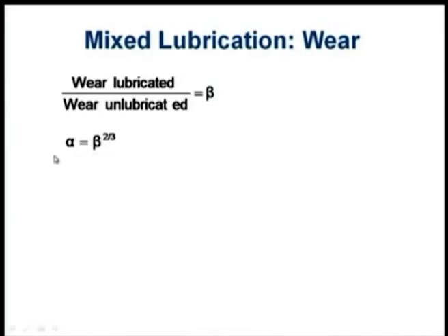So, basically wear is happening because of the friction junctions. If there is no friction junction at all, there will not be any wear. If there is adhesion, that is why wear happens, adhesive wear. If scratching or plowing is happening, that is happening because of the friction mechanism, that is why abrasive wear comes into the picture. Similarly, fatigue will happen because of some sort of confinement and some coefficient of friction causing some adhesion, loosening some particles. So, everywhere wear is related to friction.